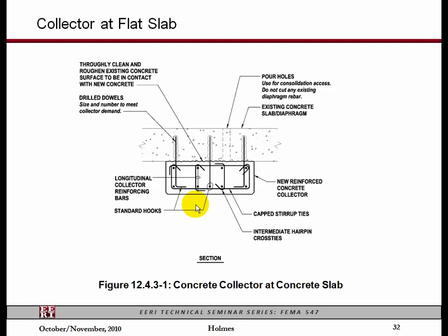So we'll look at a couple of examples. If you can use concrete as a collector, you don't really have any problems because you've got the strain compatibility problem licked. In this particular configuration, you have to figure out some way to get the concrete in here, so you probably have to have some holes intermittently to be able to cast such a collector as this.